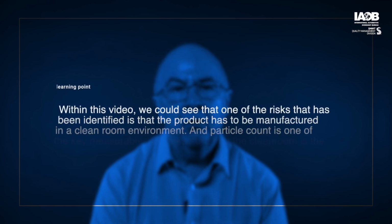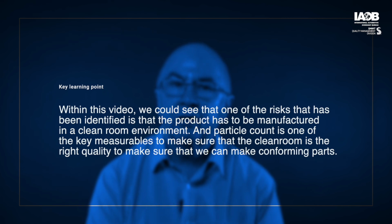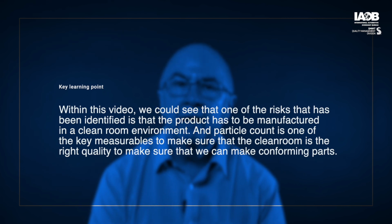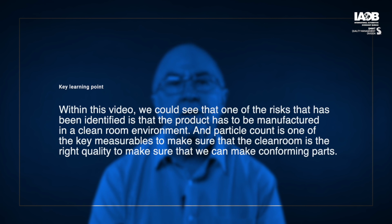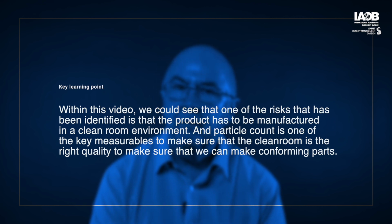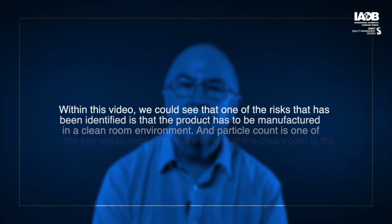Within this video, we could see that one of the risks that has been identified is that the product has to be manufactured in a clean room environment. And particle count is one of the key measurables to make sure that the clean room is the right quality to make sure that we can make conforming parts.